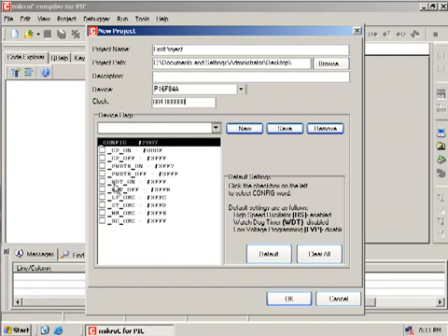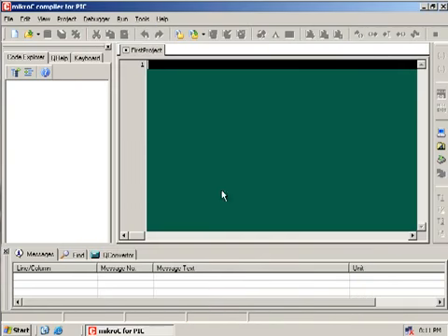You can configure them. I selected here to turn off the code protection, turn off the watchdog timer, and use the XT or crystal oscillator, and I will tell you step by step what the code protection, the watchdog timer, and the oscillator are when we are implementing the project. Okay, now everything is okay. Click the OK button. Now we can start writing code here.